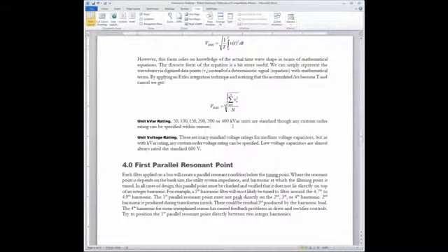But what I would recommend, in case you need units quickly and you need to buy them because you've had more failures than you had spares to put back in, is using some of these standard sizes: 50, 100, 150, 200, 300, or 400 kVAR, and just recognize the bigger they are, the heavier they are.